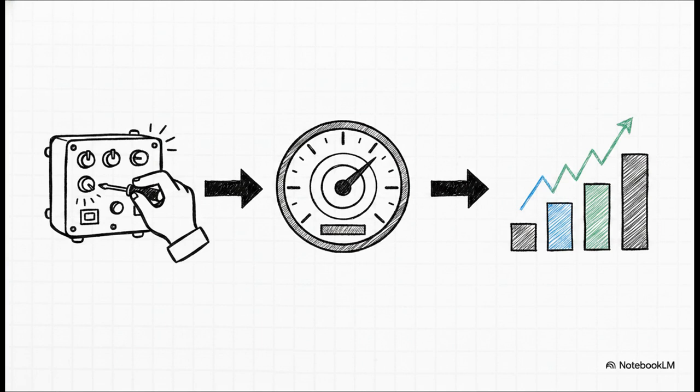Finally, start the engine and run a step load test, 25%, 50%, 75%, 100%, and watch the Woodward software to make sure that milliamp signal increases step by step with the load. If it doesn't, well, your translation is broken.